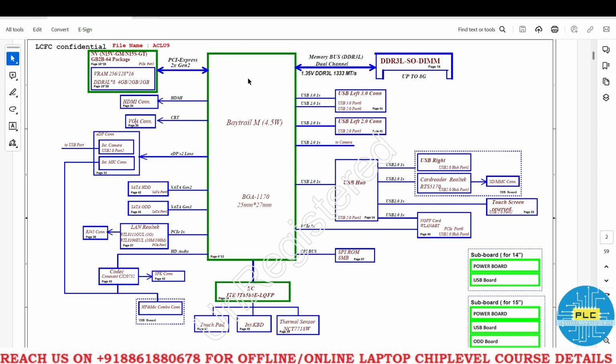Okay, see, the processor is connected to the graphic chipset, NVIDIA. Once NVIDIA is connected to the particular socket, this display unit will be primary and the processor display will be secondary. If the graphic chipset is not connected to the processor, I mean a normal motherboard, in that case the processor will access the display related signals from this particular chip and it will work.